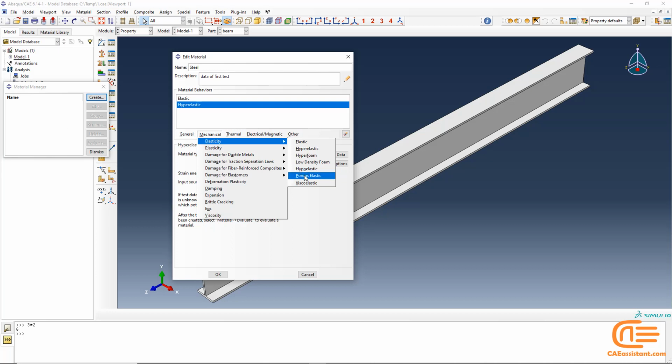A porous elastic material model defines the elastic parameters for a porous material. You can define viscoelastic behavior in a material as a function of frequency for steady state and small vibration analysis, or as a function of reduced time for time-dependent analysis.